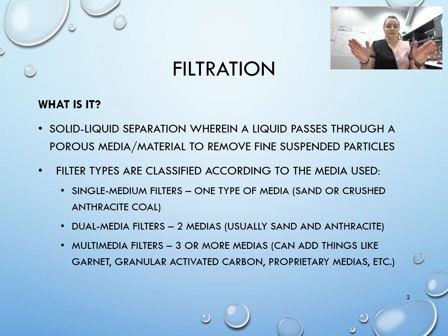So filtration, this is solid and liquid separation where we have a liquid passing through some kind of a porous media or material, and it's going to remove fine suspended particles. So we're now at a smaller particle size than we were when we're talking about things like coagulation, flocculation, sedimentation. We're getting down into kind of the nitty-gritty of removing those particles.